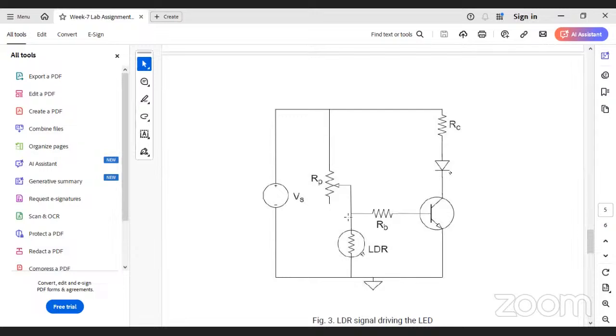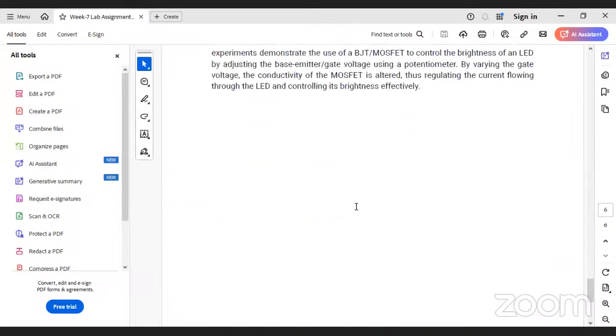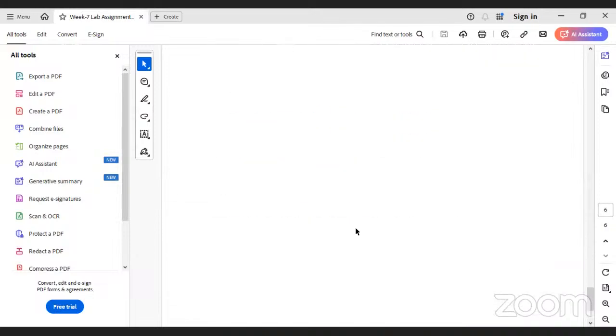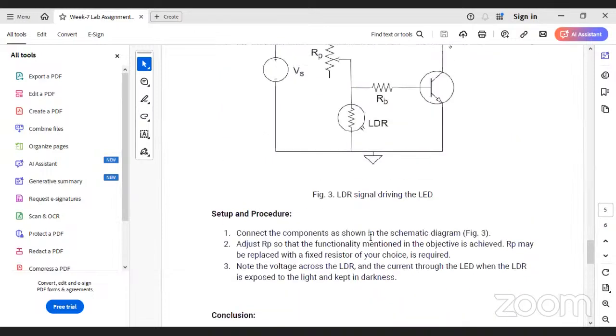Yeah, but there is another issue: if we remove the repeated sweep, we cannot measure the average voltage using the other channel available in the ADLM kit. Oh, okay, that is an issue now. That is a glitch, a problem with this kit. In this experiment you are using DC voltage all through, right? Yes, ma'am. So you can disable this. Okay.